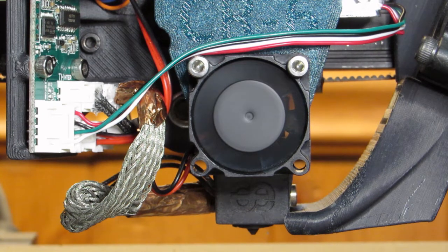If the Bowden tube is pulling off to the right, if you're facing the printer, and in effect pulling up on the strain gauge, then it's already predisposed to going, oh look, there's a bed, even if you're in mid-air. You may sometimes see the little blue light flickering when the head is slewing from side to side. It's because the strain on the top of the hot end is telling the gauge, hey, the diving board is bent, we must have hit something.